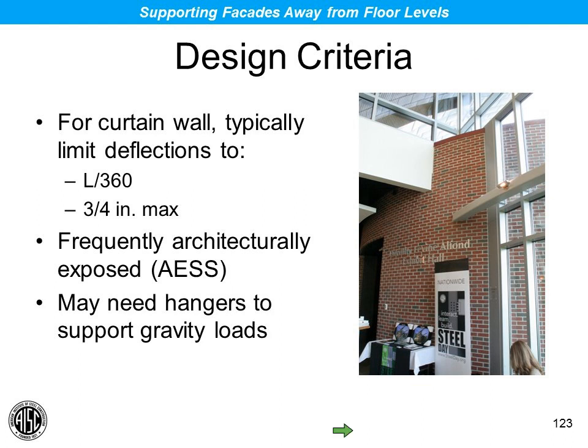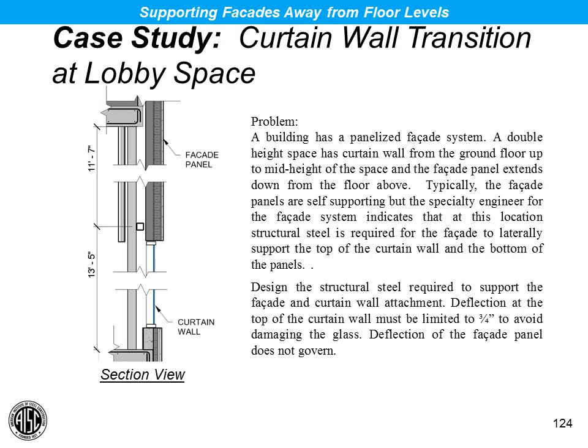And let's take a quick case study at one of my current projects. This is a building that has a 2-story space, but the glazing transitions at about midway up the building. So I don't have a floor slab back here to brace the bottom of this facade panel.